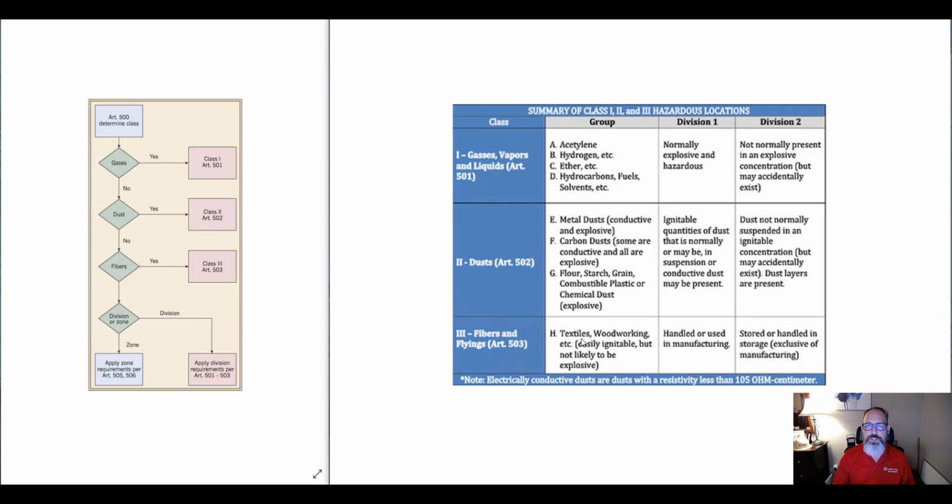The idea of this section is for you to be able to get a better understanding of where you could have a hazard, for you to know what they are. And in most cases, if it's an established facility, they've got engineering on site, they already know the classifications. So then you need to ask. Okay, you're installing something around a fuel island at a gas station. Well, what's the classification? We know what the code's going to give us an understanding, but does that company have a different specification that goes beyond what the code says?